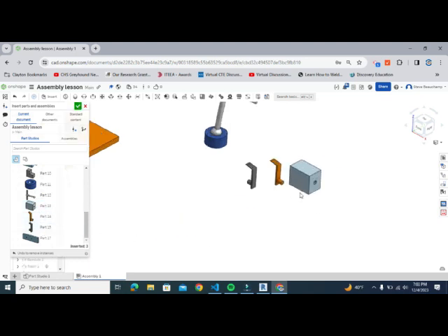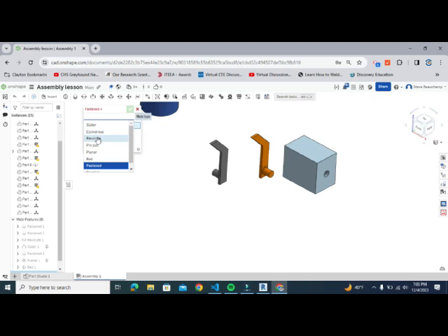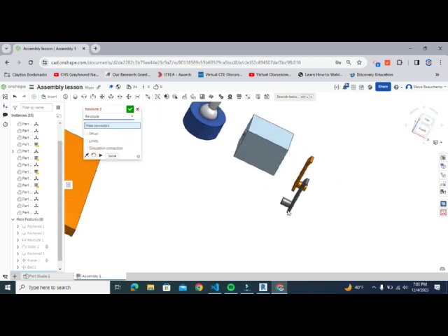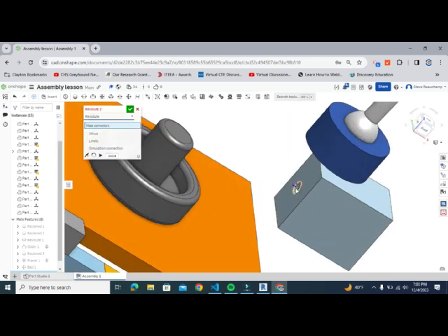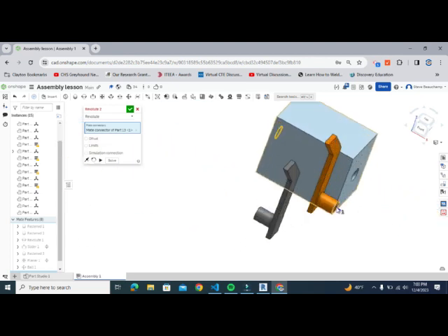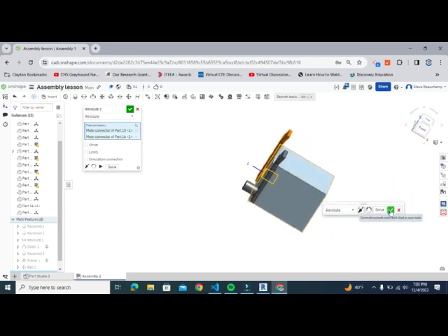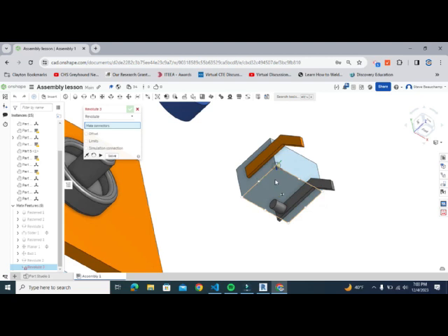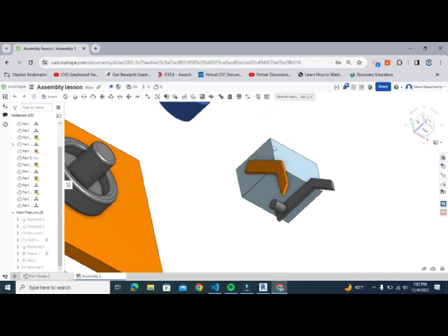We're going to bring those out, and we're going to use some familiar ones that we've used earlier. So M, basically what I want is I want this arm to be on this side of the box. So I'm going to grab that mate connector there, okay? And I don't want to have to offset it. So I can choose this mate connector, but if I choose this one down here, I'll click that, and now you can see it goes all the way up to the box, which is how I want it. And we'll hit check. Okay, we can fix the box in place here, so let me close that, right click, fix the box in place, and now you'll see that this rotates like it's supposed to.